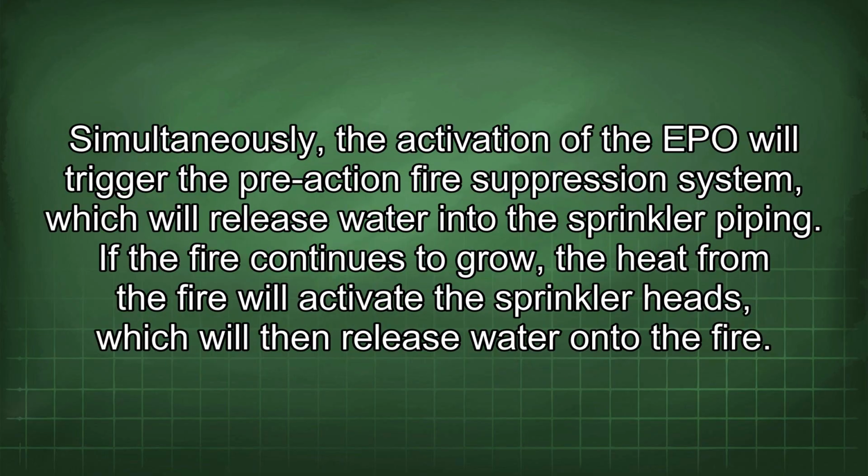Simultaneously, the activation of the EPO will trigger the pre-action fire suppression system, which will release water into the sprinkler piping. If the fire continues to grow, the heat from the fire will activate the sprinkler heads, which will then release water onto the fire.